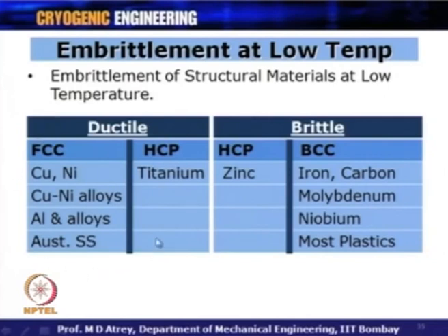So, all these materials can definitely be used for cryogenic temperature, provided they satisfy other requirements like ultimate strength and yield strength, etc., depending on the failure mode for those particular materials. While these are all materials which remain brittle at low temperature, and therefore, they cannot be used unless specifically required and specifically evaluated at lower temperature. But mostly these materials will not be used for cryogenic applications.